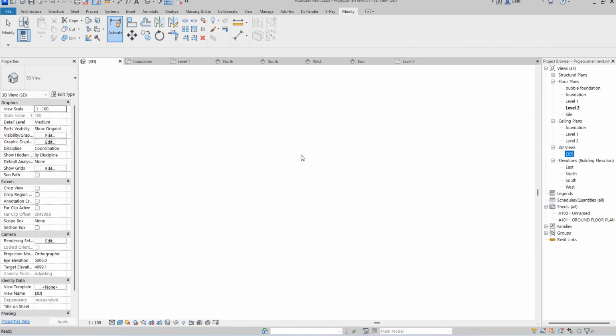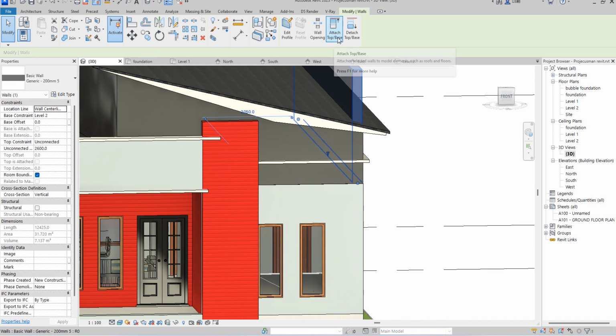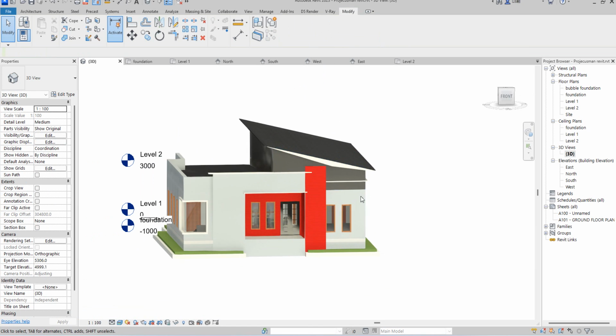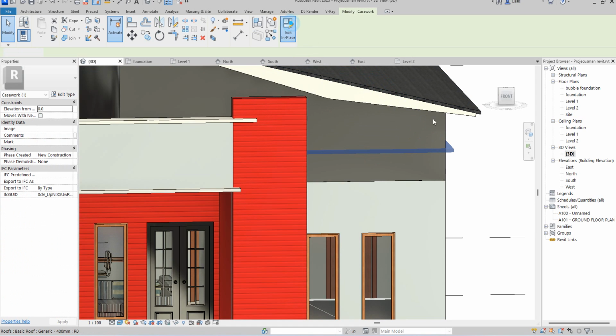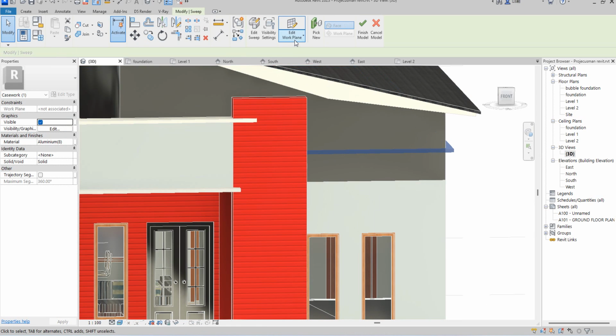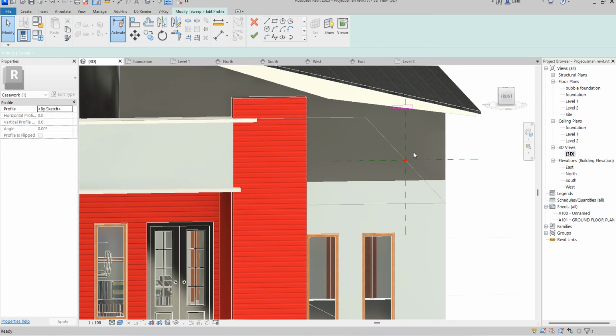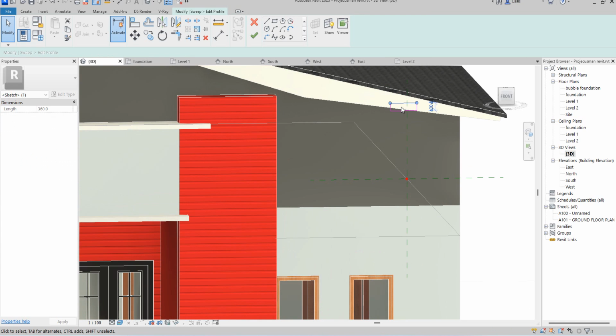So I can now go to 3D, then I'll attach this to the roof. So attach it to the roof. Okay, so that aspect is settled. Can decide to edit this thickness. I think it's light for me, so I want to edit this thickness. I'll just say part, clear the part and edit the part. So all I just need to do is to drag it up a bit or change the value. So like that is okay.